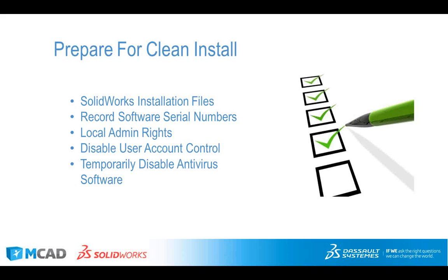You can go straight to the latest service pack instead of trying to install from the DVD and then upgrade later. Don't be surprised at how long it might take to download the complete data set. It is over 7 gig now, so depending on your internet speed, it can take a good while. You also want to check into privileges. You're going to want to be able to disable antivirus. That definitely speeds things up, but it also might be critical to allow the install to write to the registry.